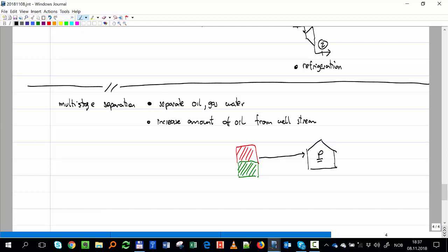But in terms of calculating the GOR, we can neglect all the rest and say this is just this multistage separation. It's really what drives this GOR, which is Qg and Qo. And if you use a different process, I'm going to get a different GOR. We're going to see that in a while.